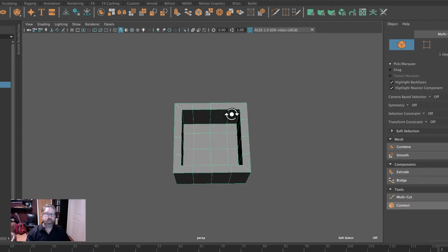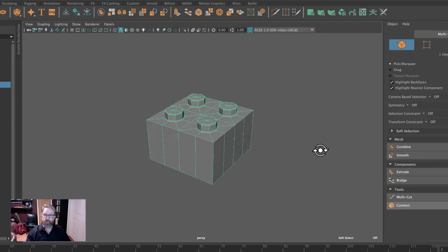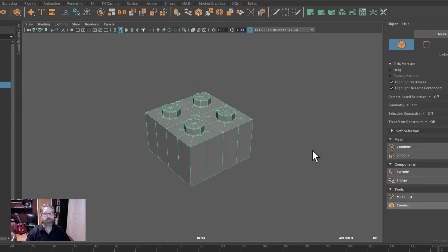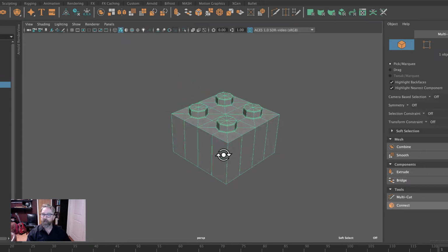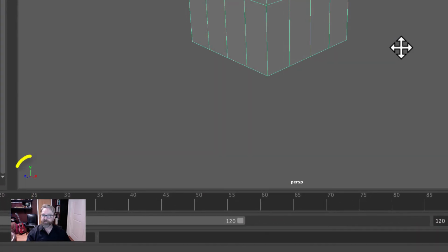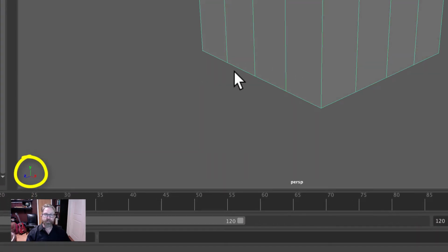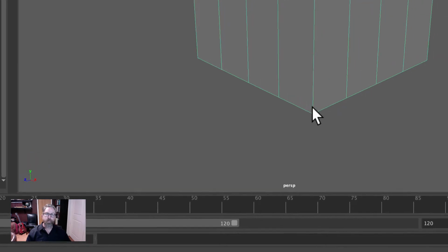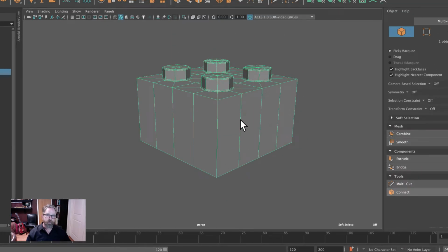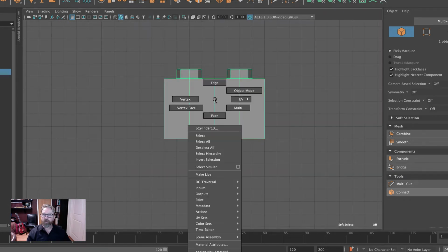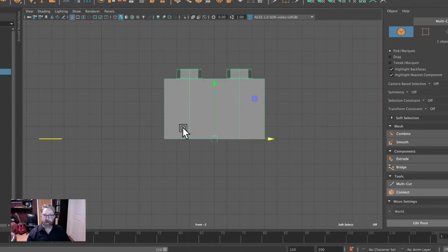All right, because in order for us to create our angled brick version with the recess, we need to start with an unbeveled version. All right, we want to be Z forward. And we're going to go through that exact same process of creating an edge loop 0.8 up from the bottom in order for us to create the 45-degree angle. Okay, we're going to jump into the front view, and we want to put the pivot back to the top. So right before you exported your 2x2 brick start, you'd put the pivot at the bottom. We're going to put it back to where it was.